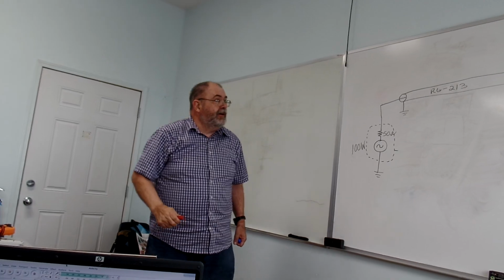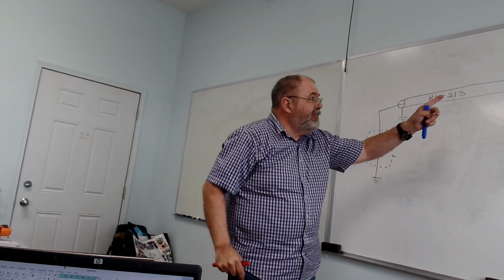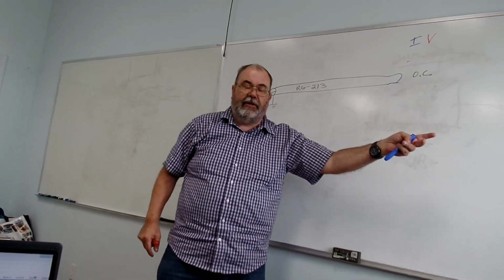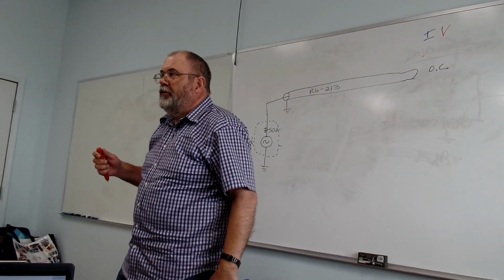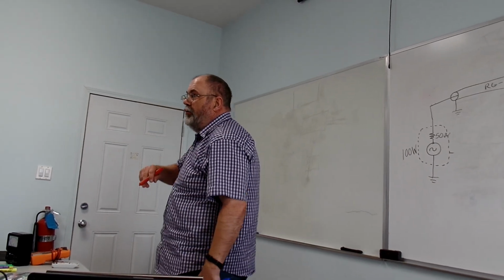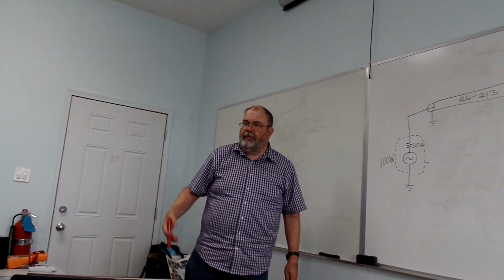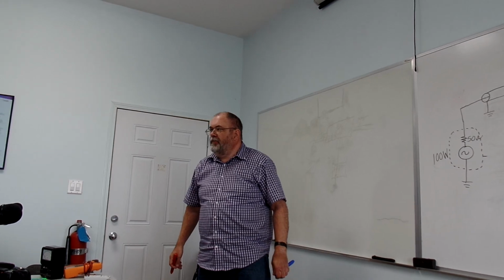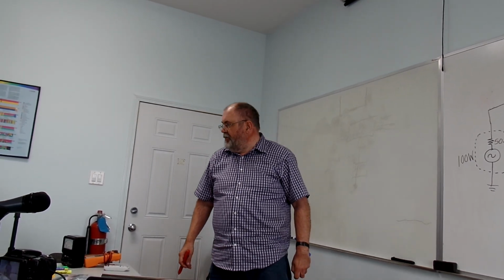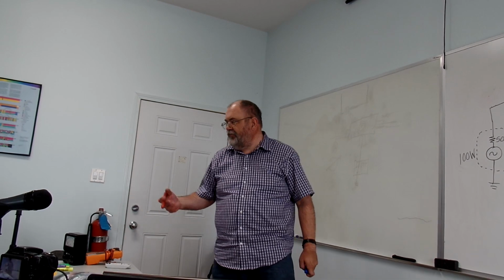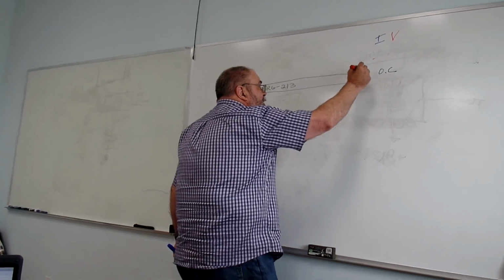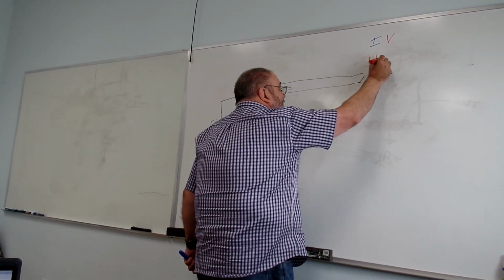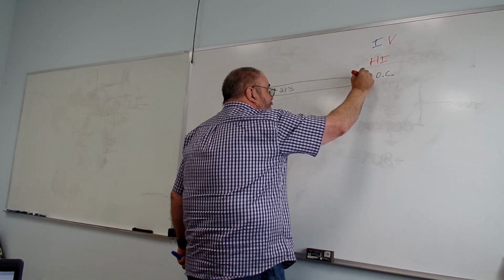Okay, so at the end of this coax cable, once our transmitter starts transmitting, this is an open circuit. So let's talk about the voltage. Do you think the voltage is going to be high or low at that point? At an open circuit. Depending how long the coax is. Doesn't matter how long it is. You've got infinite resistance, a very high resistance, which means the voltage will be high. At the end, we're talking right at the very end of the cable here.